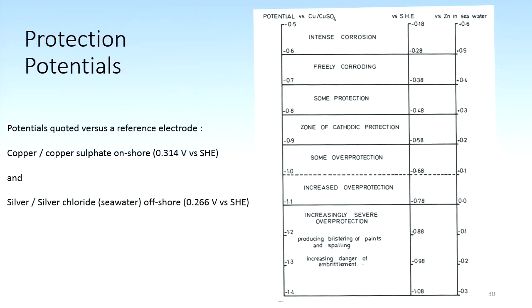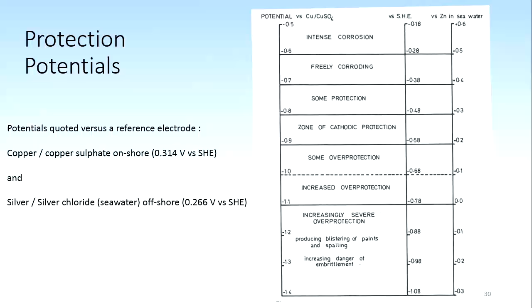Quick follow-up question on this, because I've talked to some consultants about this impressed current system. What they're telling me is the anode has a range of what they throw the current to. It's called current throw. All electrodes have a current throw. So there is a radius that they can reach. Is there a limitation? What controls the range of this? The soil resistance. So it links back to my question just now. So you need to do a bit of layout planning to place your anode so that the entire part is covered. You have to know what environment you're putting it into.